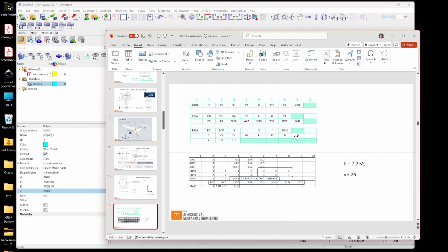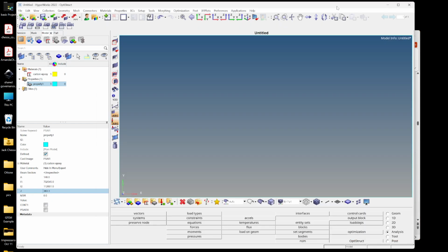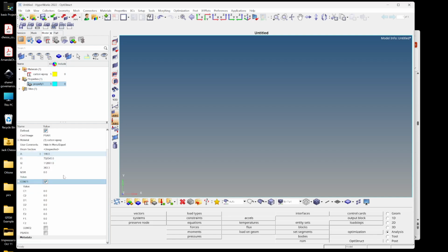So that is like a continuation line. So in HyperMesh, when we have those, you'll see this checkbox for continue one. If you click on that, it'll expose more values. These are the fields in the second line of the PBAR card.